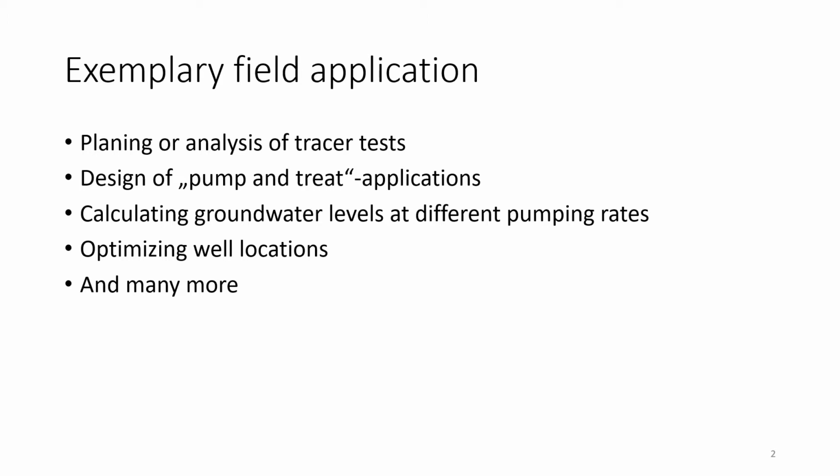Also very classical is groundwater management: how does the groundwater level change at different pumping rates? For example, you want to install a new groundwater well and extract water from it. You can see how far your domain will be influenced, and how much the groundwater level will decrease at different pumping rates. All those questions might be difficult to answer analytically, but numerical simulations are quick and helpful.